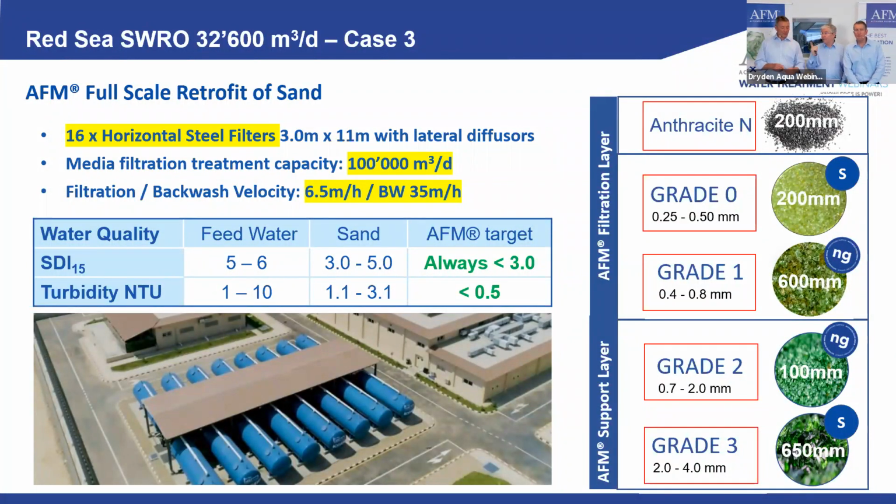Important to say for the algae bloom, just to mention it here, the anthracite removes only the big chunks. The fine particles of the algae are removed by our AFM. Of course, anthracite just gives you room for filtration. It gives you a longer time between backwashes. I mean, really AFM is for fine filtration. And if we get heavy loads, we need something else. So anthracite might be one of them or another solution. But we are running out of time.